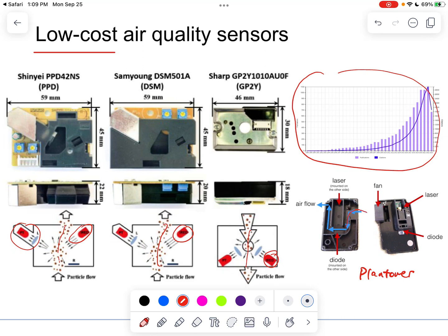Okay, so for the plant tower sensor, it's similar. You have the airflow going through the channel here, and there's a laser, let's say an LED light, that shines radiation through this channel. The laser diode is not placed at an angle; it's just below this laser here, right? The gas stream is going across, and the sensor is placed on the bottom, directly on this plate here. So it's still collecting the scattered light signal.